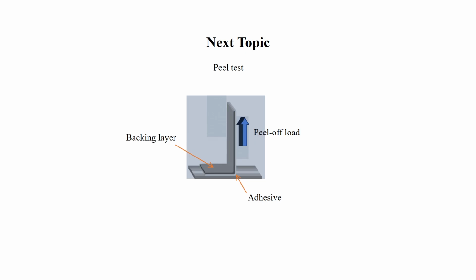And then what we do is we try to find out the kind of adhesion given by this particular adhesive glue on any surface. So let us say we paste it like this on the substrate, the adherend, and then we try to lift it. So this is a very simple experiment for finding out the adhesion strength of an adhesive, and when we lift it we can do it perpendicular like this, the picture that I have shown here, or we can do it at some angle like this, or at some angle like this.